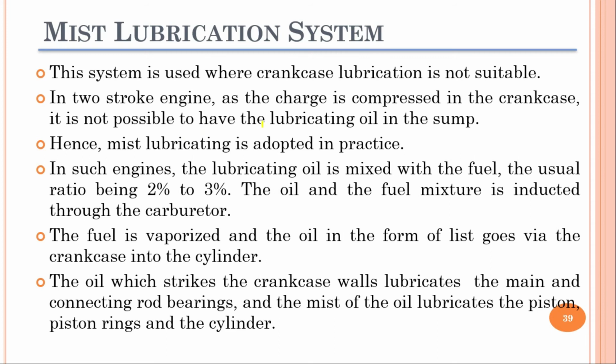If you remember, in anybody's home you may have some old Vespa or a Kawasaki motorcycle, what they do is they basically add some amount of lubrication oil along with the fuel. And the amount is approximately 2 to 3% of the gasoline.